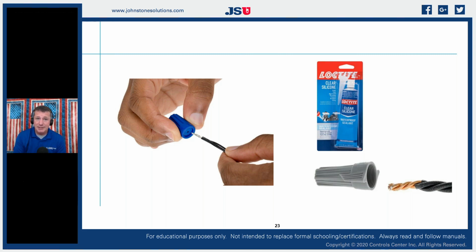Well, what that means is no splices. Or if they're spliced, they need to be properly spliced. So we find a lot of times our issues in our communicating systems are oxidation on the copper or corrosion on ground terminals. So pay special attention to our wires.